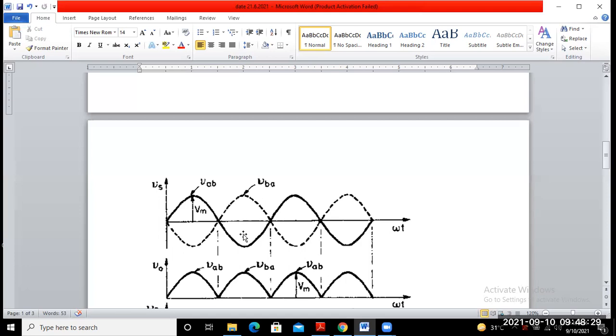So you will get at this point a maximum negative voltage. That will be this one. If this point is your Vm positive, that means up to this point you will get the maximum Vm. Is it not? So this one is represented by maximum Vm at an angle of 270 degrees. So we already explained the operating principle from 0 to pi, which diodes conduct